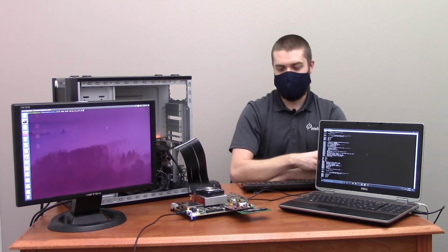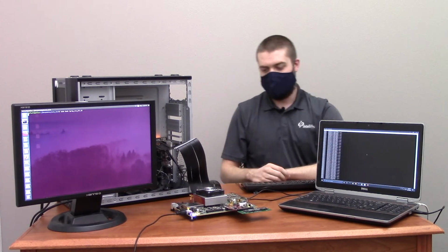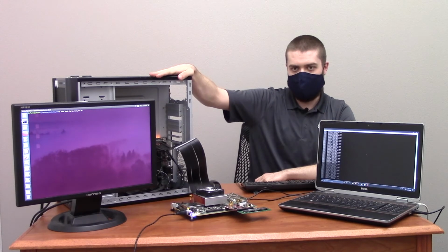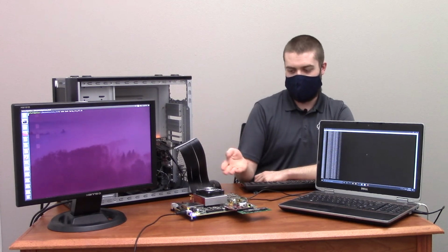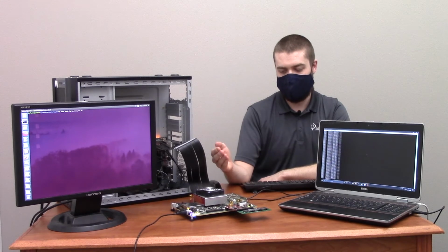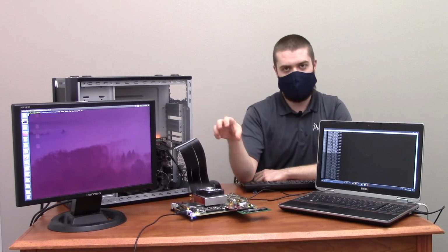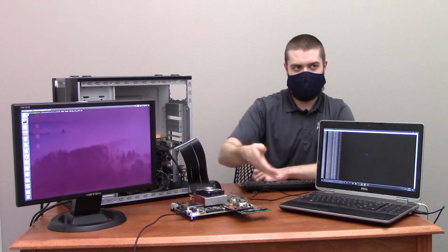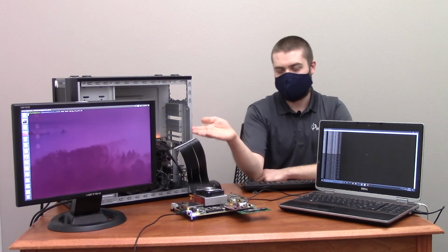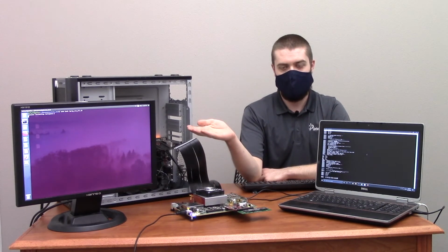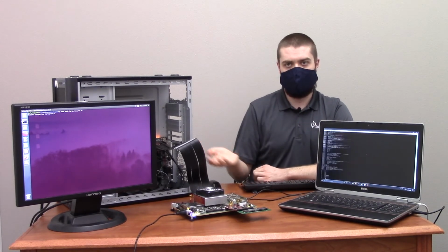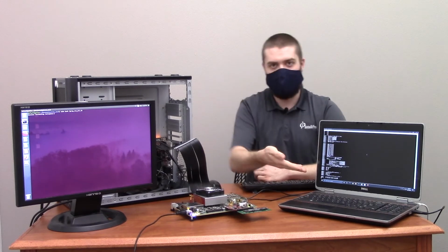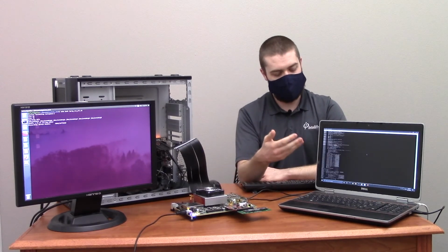So now I'll be running the demo for you. What we have here, I'll start the demo and then I'll describe it to you. So what we have here is our host PC connected via the PCIe cable to a Xilinx VCU118 development board. This holds our NVMe Bridge IP product. Then on this end we have a Samsung 970 Pro SSD acting as the NVMe endpoint. What we're using is the FIO benchmarking tool to run a series of commands demonstrating the performance of the IP product. And on this side we have another computer displaying our debug UART prints.